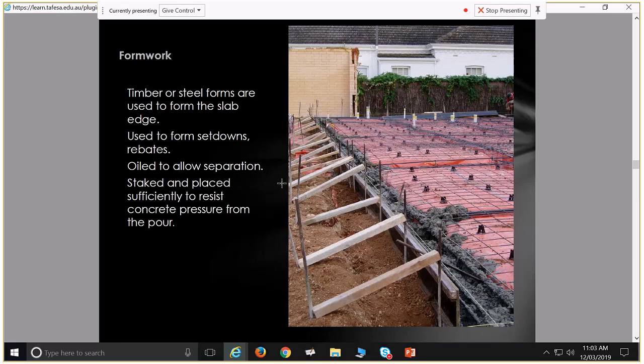If you go pouring lots of concrete into a very tall form, then there's a lot of pressure at the base that can pop it out. So it's not only important to think about the design and the structure of that formwork, but also about what height of concrete you're laying in each section before it starts to go off and solidify.